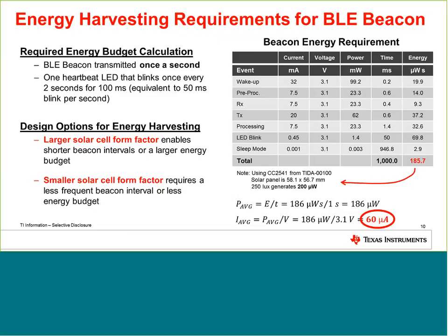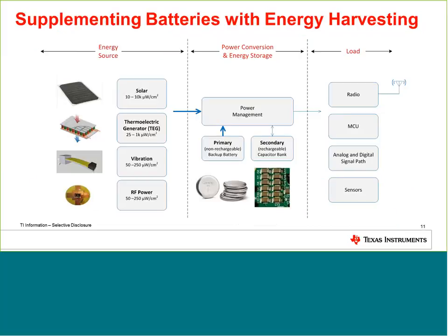We just saw in the previous calculations that our sub-gigahertz is going to consume 0.6 microamps, so that is 100 times more for the BLE beacon. So if we are going to go with a BLE beacon, we cannot easily run it on a battery for 10 years, or the lifetime needs to be shortened, or we need to have an additional energy source to supplement these requirements.